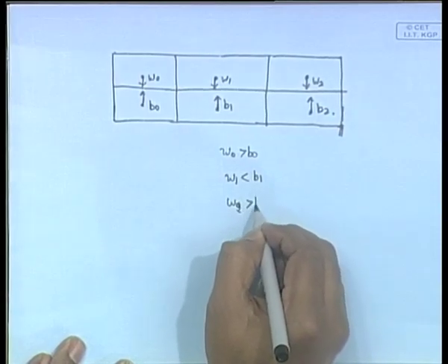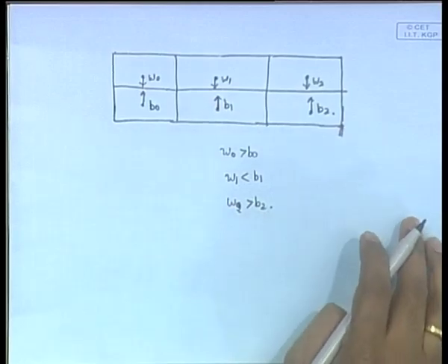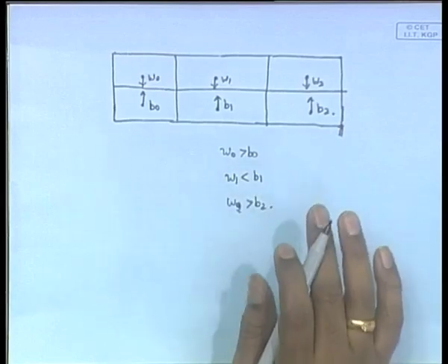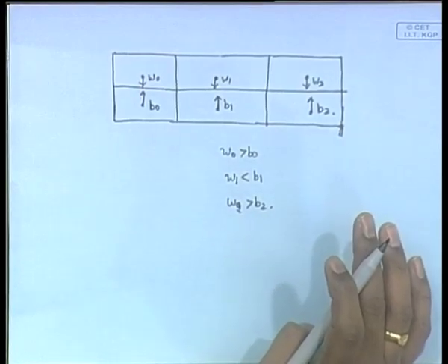Okay. So in general, when you look at a ship, this is for a ship, I mean we are comparing it for a ship. So what you see is that in general if you have higher weight on the aft side or if you have higher weight. So, according to this distribution what I have drawn here, in the middle part, in the mid portion of the ship, you are actually having higher buoyancy, because the volume is in general higher there, the ship is full as we say, it is very thick there, and therefore the volume is more and the buoyancy is more.